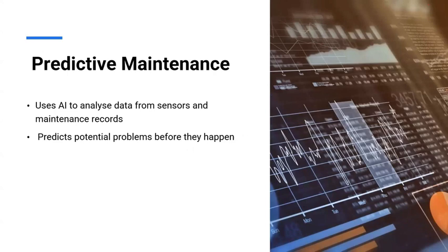Then in that, what is predictive maintenance? As I have said, predictive maintenance uses sensor data to give information on the current state of health of each component, and how long each component is going to run. It can say valves are going to run for the next 5 months, and the injector is going to run for the next 2 years. It can say it completely like this.